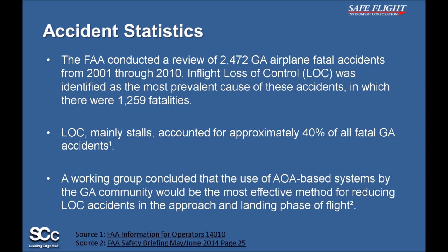A working group concluded that the use of angle of attack-based systems by the general aviation community would be the most effective method for reducing loss of control accidents in the approach and landing phase of flight. We will be getting into more detail about why they made this claim later on in this presentation.